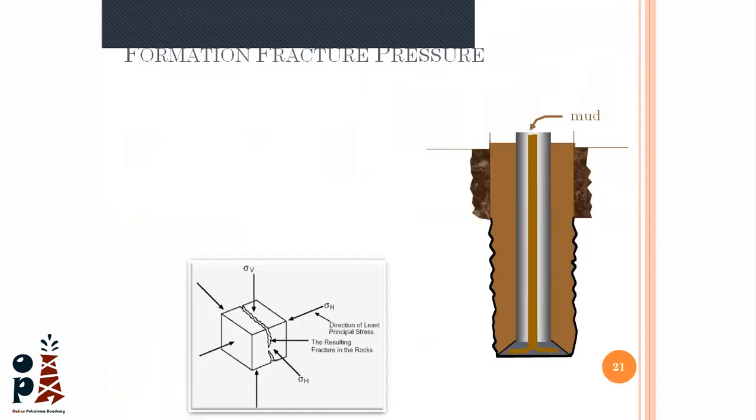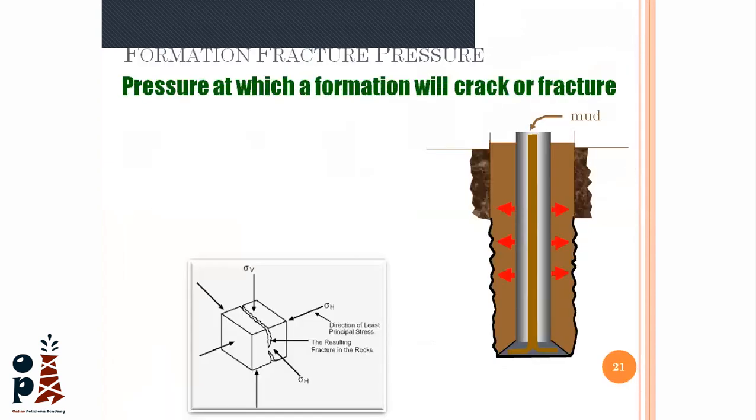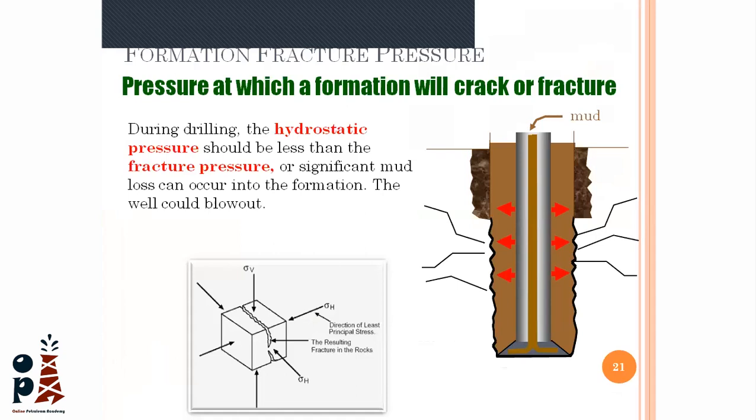Okay. The fracture pressure, I talked to you about it. It is the pressure at which I will break down the formation. There are a lot of details regarding the fracture pressure in this slide, but it is not our scope. The vertical stress, the minimum horizontal, the maximum horizontal, would take too much time to describe. So I will be satisfied with the concept of the fracture pressure, which is the pressure at which the formation will crack. And we calculate it when we are drilling for the first time in any exploration area.